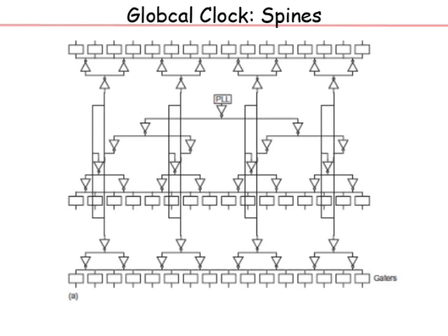It's very wide, very low resistance, and it's being driven in parallel from all these spatially different regions, so that the skew across here is kept almost close to zero, because it's being excited from multiple different spatial points along this horizontal line, here, here, here, here in parallel. The resistances are also kept very small by using very wide wires, so that the relative skew horizontally is kept very small. Same for this one and same for this one.